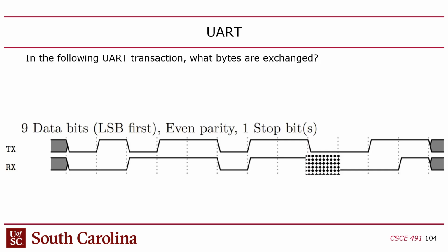So this is an example of what's called an erasure, which is where there's an error, but I know which bit is an error, right? Now, the problem is, unfortunately, with UART, I don't think that's typically true. If there's an error on the channel, I don't think the receiver knows which bit is an error. The reason I'm doing it here is it's just an exercise for you to be able to understand. This is just a kind of manufactured question.